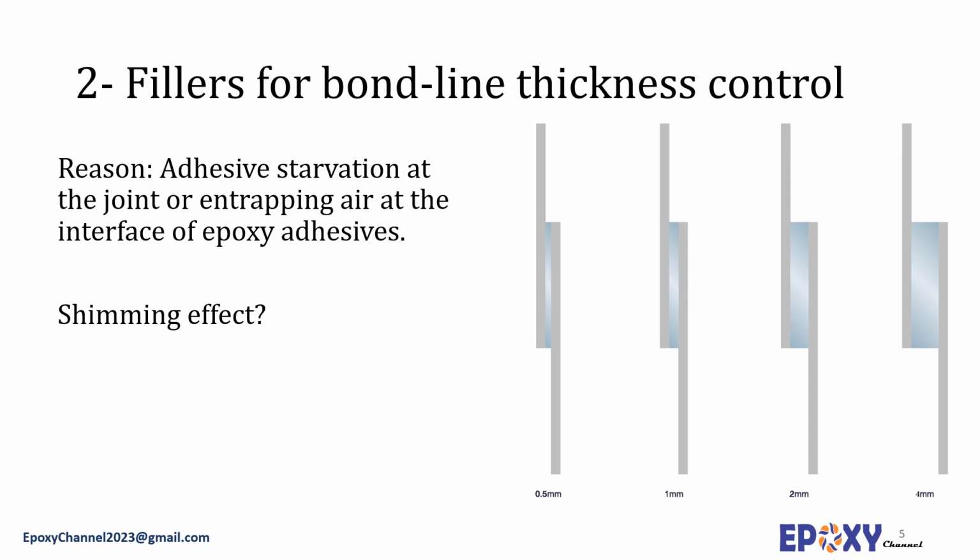To obtain a practical bond line thickness after the application, fillers are incorporated. Ordinarily, the objective is a bond line thickness of 2 to 10 mils at pressure as high as 5 psi at the curing temperature. It should be noted that the viscosity of the formulation could drastically reduce at elevated temperatures, and there is a risk of adhesive flowing out from the joint area before the adhesive is completely cured.